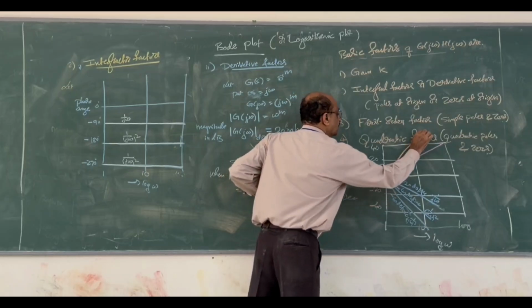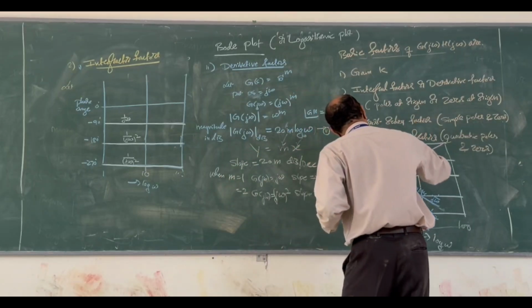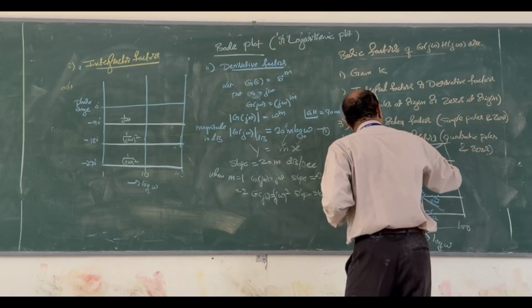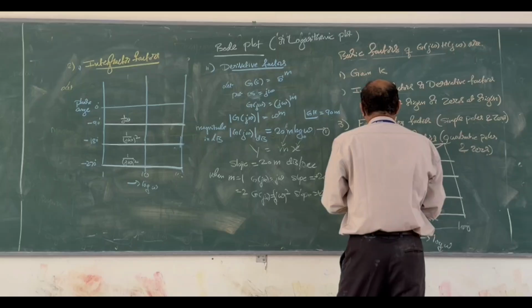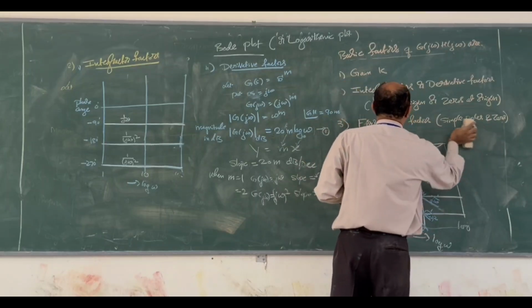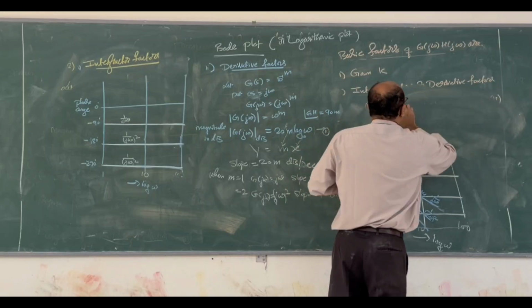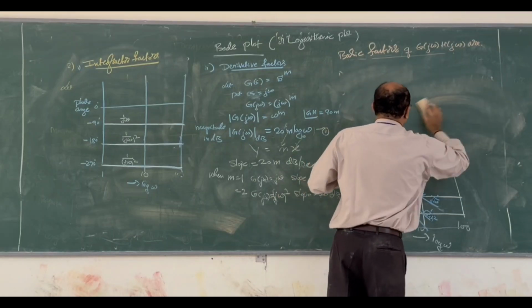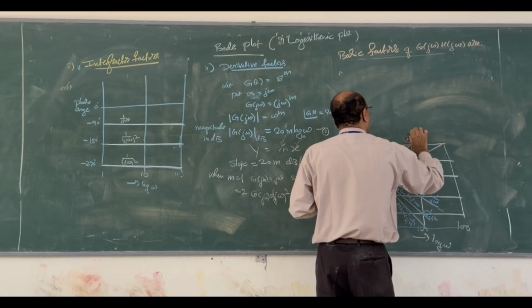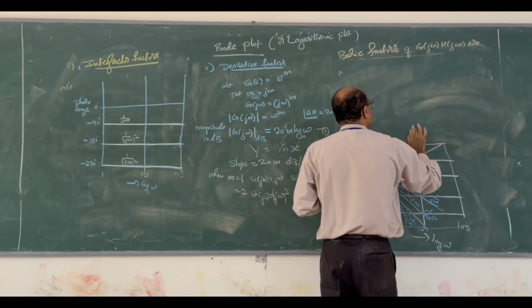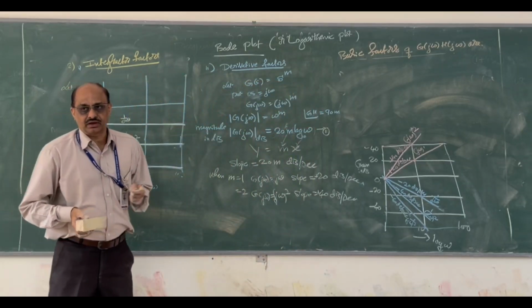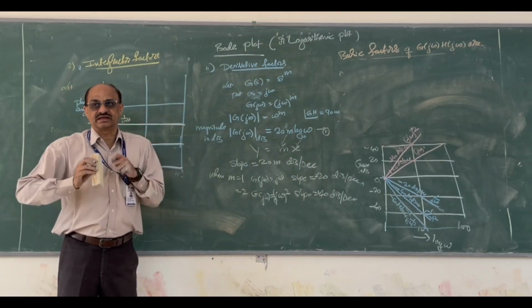To draw that, it is plus 40 dB per decade, for j omega squared, like that. It goes like, if I have 3 zeros, plus 60 dB per decade.